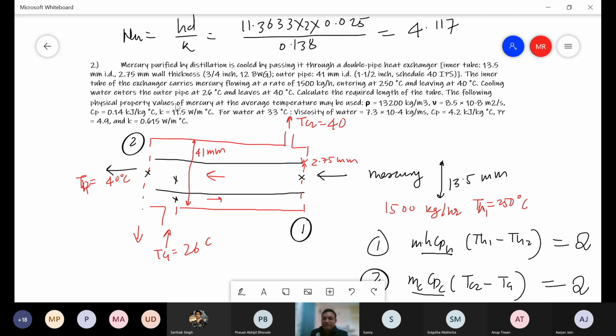What do you say? No, so it should have opposite direction. It is not possible because the outlet temperature for cold and the hot fluid are both the same. So even though that part is not given in the problem, just by looking at these temperatures itself, you can conclude that the only contacting pattern possible in this case is a counter current flow. Yes or no? Isn't it? So that's why I have taken this counter current contacting.